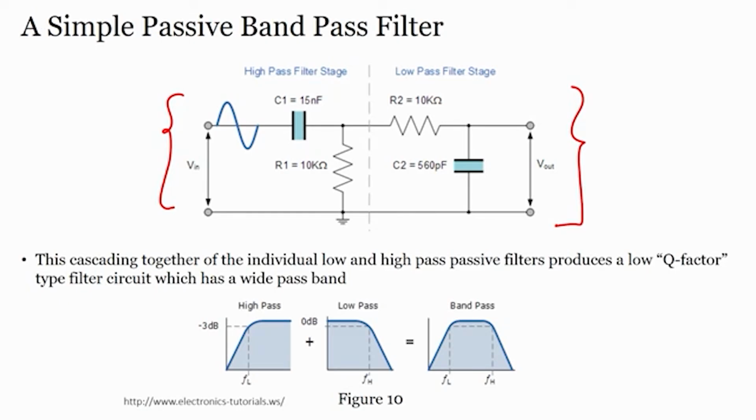Because it is so simple that by integrating the high pass filter to the low pass filter, we can get a band pass filter. Now, we should all remember that in high pass filter there was a capacitor at the input, and then the capacitor was in series with a resistor. In low pass filter, resistor was in series with capacitor, right. Output voltage across the high pass was measured across this resistor, output voltage across low pass was measured across the capacitor, right. So, if I integrate both, it becomes a band pass filter. How? So, you see